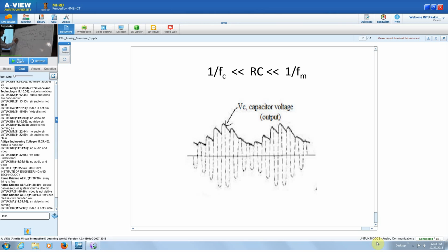Whereas the input decreases now, because you are having a negative cycle reduction and then going up to the negative cycle. Then again it comes here, and when the input is more than this capacitor voltage, the diode starts conducting. But during this period, the capacitor has to discharge.